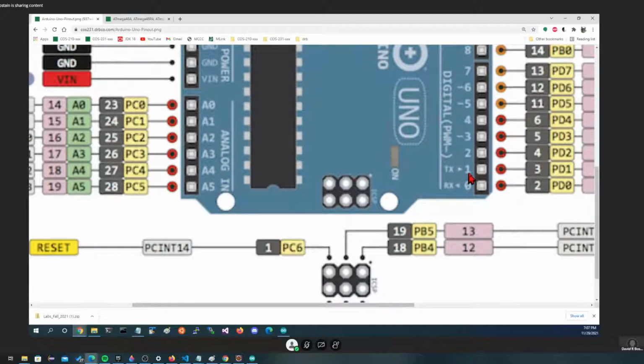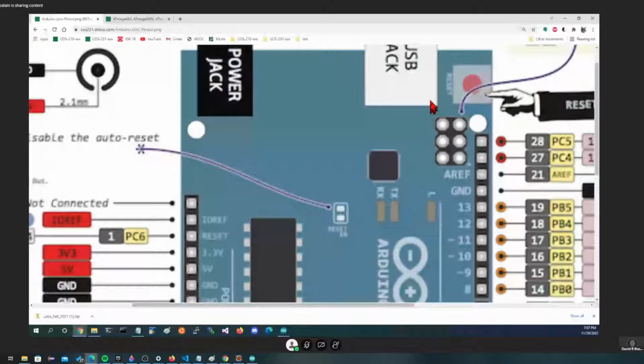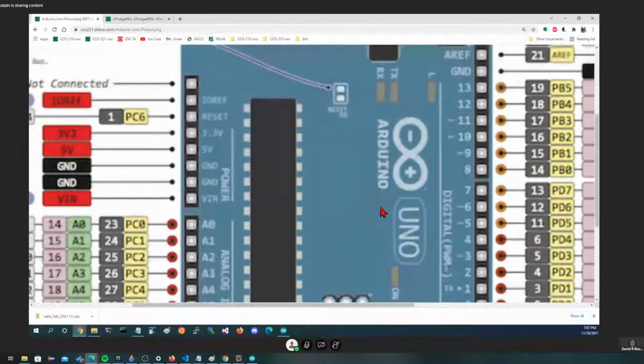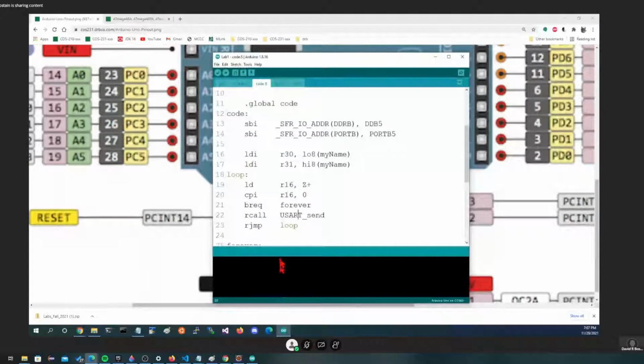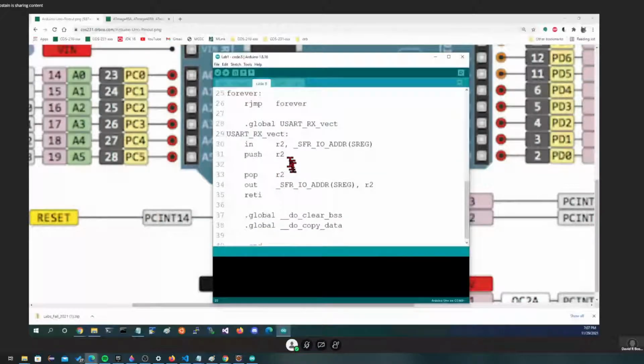So it's going to come out the transmit pin. If we had data coming in, it would do just the reverse. It'd come over the USB into this. We'd see a receive light blink. It would then go in the receive pin, and then it would cause in our code this receive interrupt down at the bottom here to execute. We're not receiving anything, so we won't talk about this until we do. But just be aware we already have some code down here that knows how to receive data on the RS-232 line.